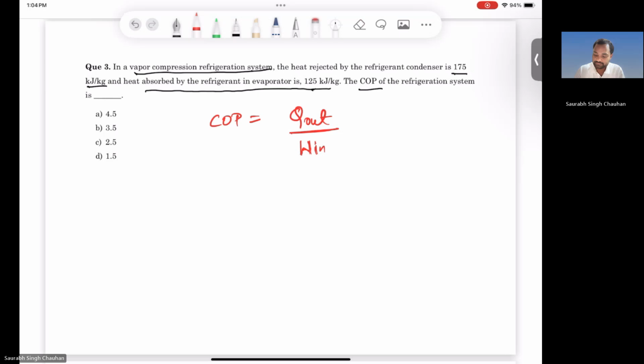Okay, so this heat is removed basically by the evaporator, right? So this is by the evaporator and this by the compressor. This work is provided to the compressor. Okay, and for a heat pump, the purpose of a heat pump is not to remove the heat, it is to dump the heat. Okay, so there your purpose is not to remove the heat, it is not the Q out, this is Q out plus this work.